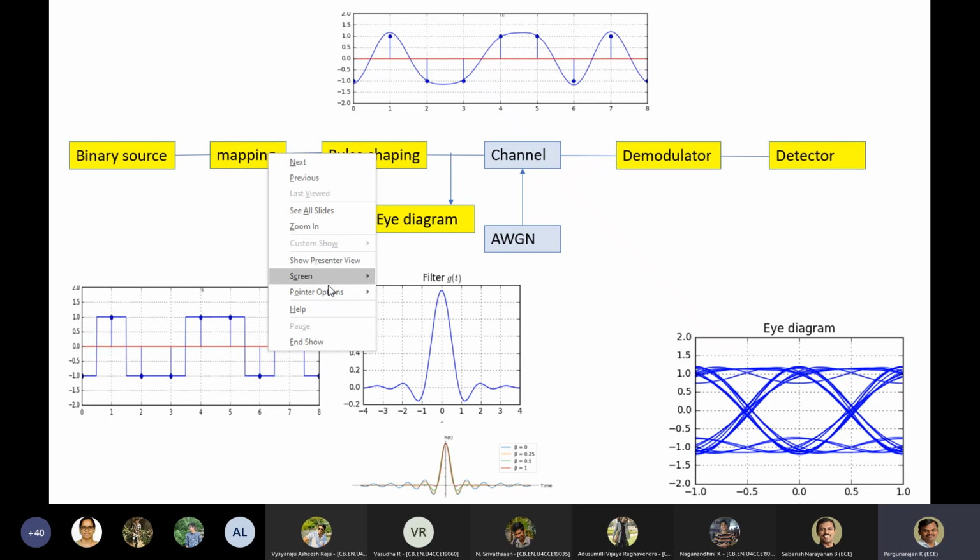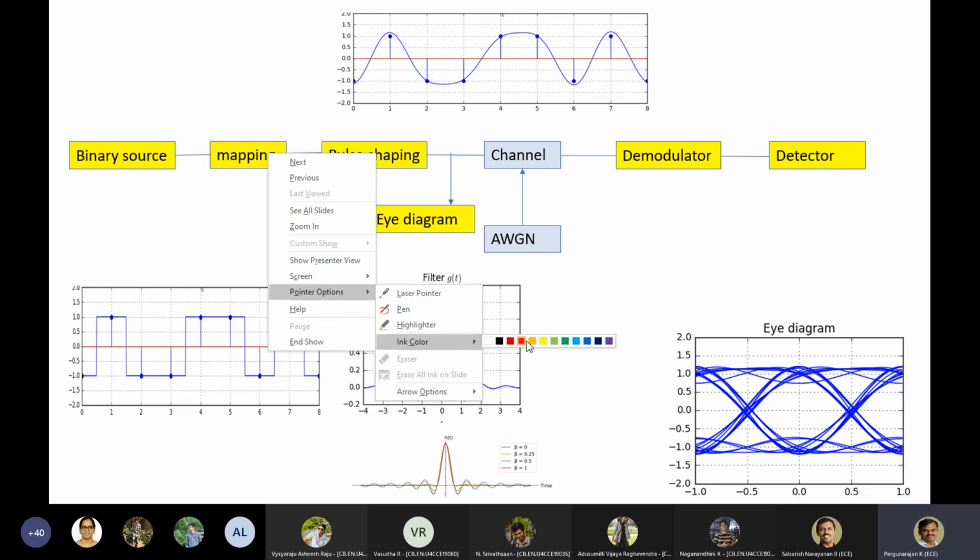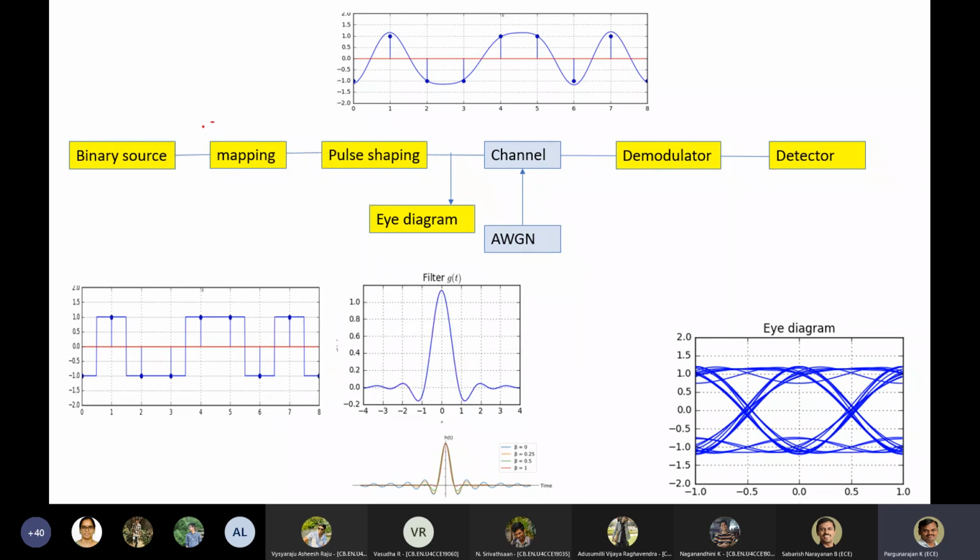So this particular mapping does some representation. Here I have 0. I'll try to express 0 with a pulse something like this, starting high, falling down and keeping low. If it's 1, I will go with the reverse. This is one of the line coding techniques, the Manchester coding technique, or you can go for NRZ, or a normal plus and minus representation.